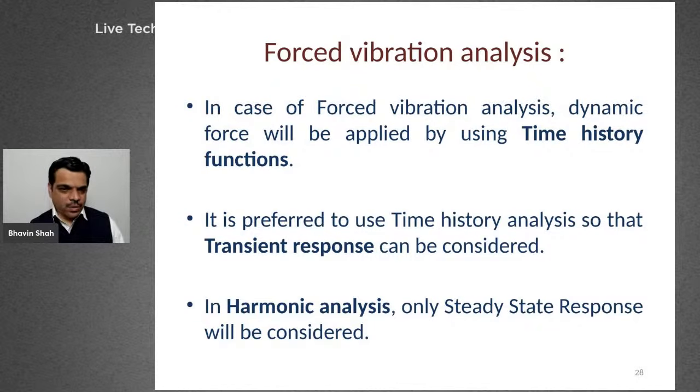Now, why is it required to apply the load using time history functions, which I mentioned in the second para? It is preferred to use a time history analysis so that the transient response can be considered. So what is transient response? We will see in the next slide. In harmonic analysis, only the steady state response will be considered. So let us see what the transient response and the steady state response are.